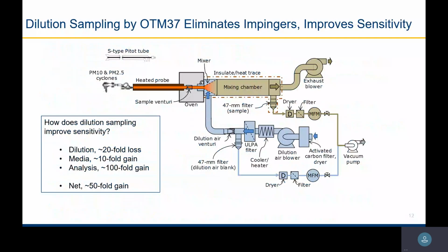And also ones where you don't expect there to be any real CPM, the condensable particulate matter. On some sources, for instance, a gas-fired power plant has very low sulfur. Lots of times they're running on very low sulfur limits from pipeline grade natural gas. Where are they getting the CPM when they do 202? And this method will help eliminate some of those precursors that they were getting because of the long test runs that they were required to do. They could have some interference, or some method problems during those long test runs. So I see some advantages of that.